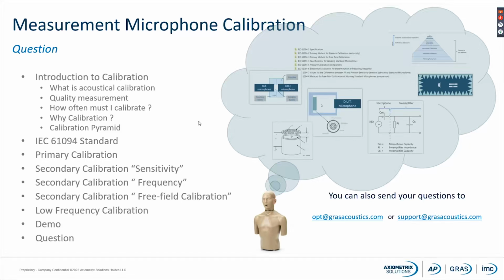So with an externally polarized microphone, when you start doing calibration, wait about 1 minute after you have applied all the supply voltage to the microphone before you actually do your calibration.